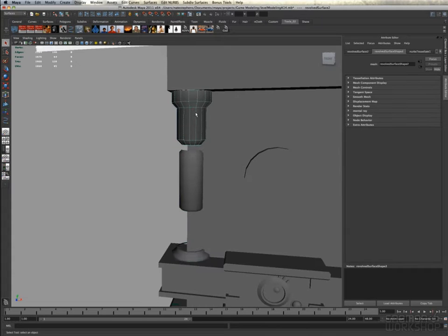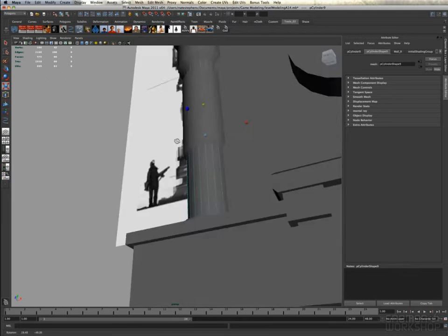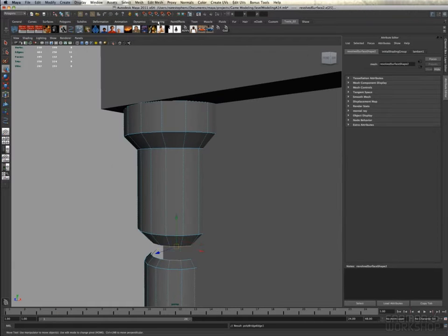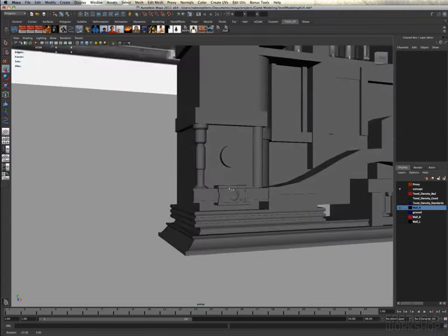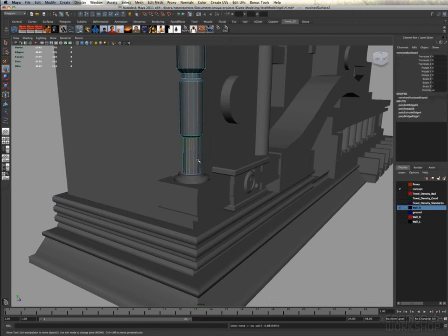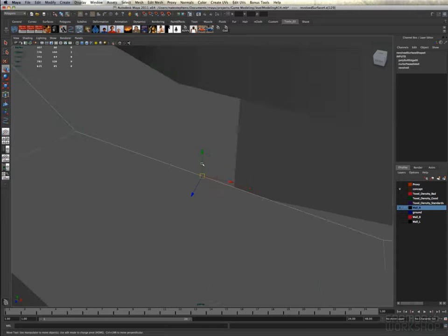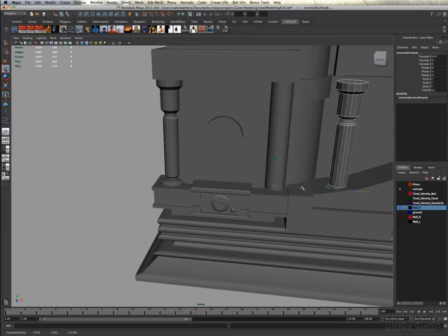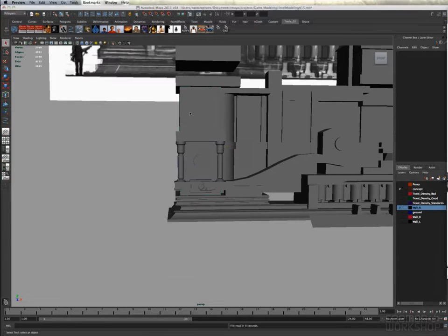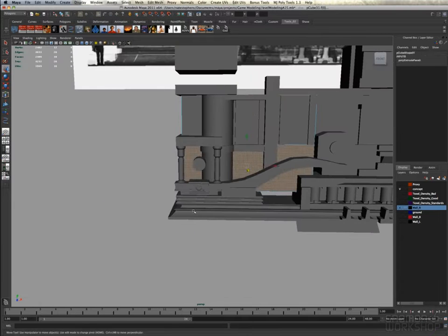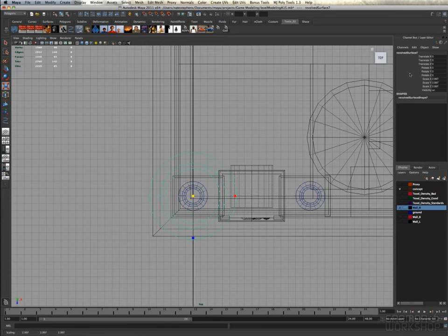There we go. Could I have made this out of just starting with cylinders? Probably. But I find working with curves is the most accurate. Plus it laid out a set of UVs for me. See right here I'm using the bridge tool and the extrude tools to add on to this section. And once I get this right, we'll go ahead and duplicate it and throw it to the other side so we don't have to do the same thing twice. And looking at Cecil's concept art, I'm not trying to match exactly what he drew. More, I'm just trying to get the general idea across.